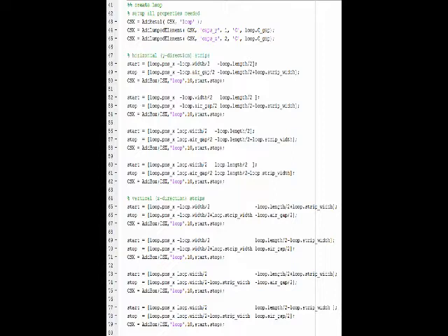To start this, we have the starting point and stopping point taking the loop parameters such as the X direction, the width, and the length of the structure, and using the addBox function taking those starting and stopping points as inputs, we save it in the CSX structure. Therefore, one piece of the loop antenna is created. Repeating the previous process, we have the Y direction strips created. It has 4 small elements.